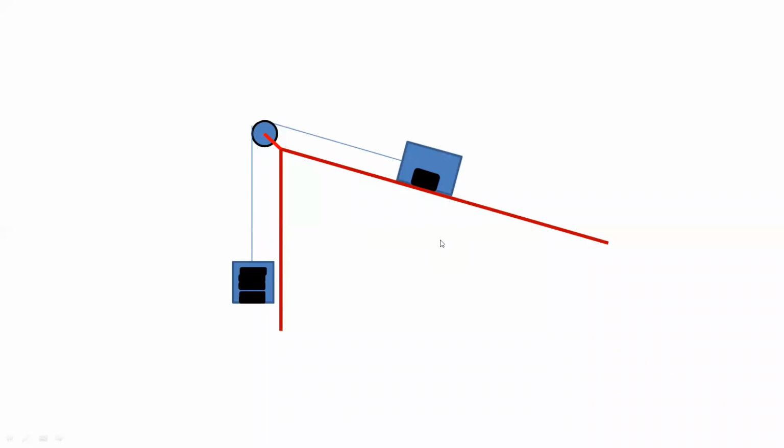For this condition, the friction force will be the maximum frictional force, or the limiting frictional force. And beyond this, if you add more weight, then you can see the complete motion. That is the dynamic state. This weight is nothing but the P value in that formula, P minus W sin theta upon W cos theta.